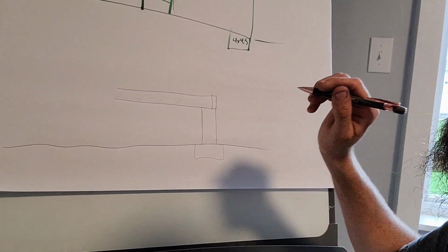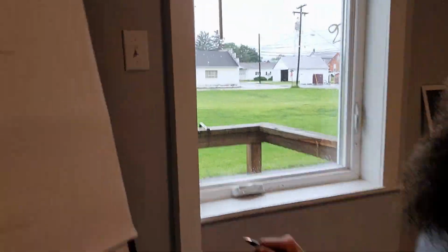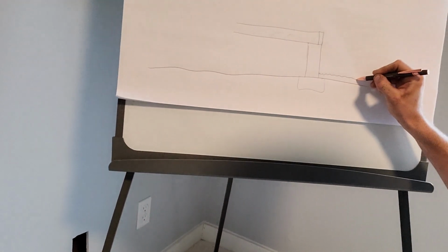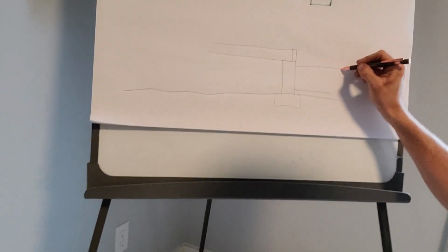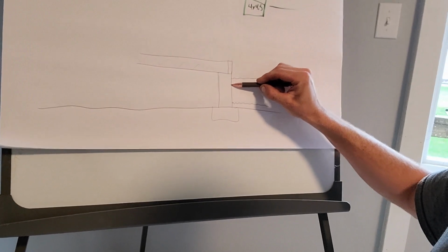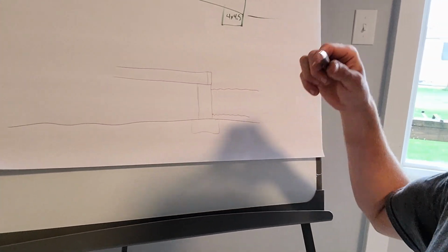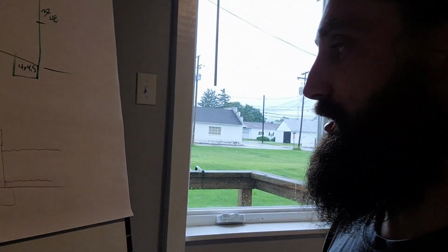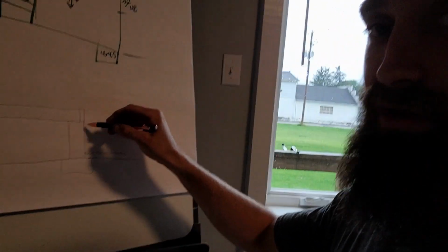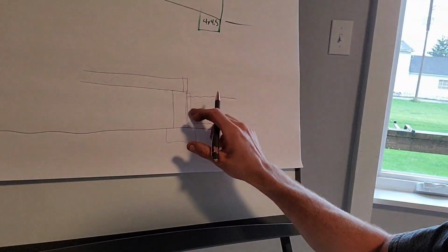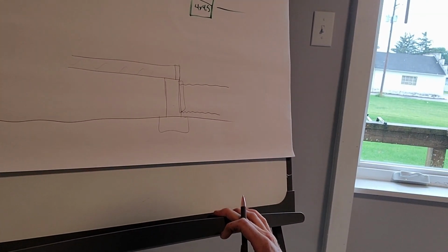Now, what we need to take note of, especially in an area like this, which was an old commercial building, is where is our exterior grade? Okay, is that grade 3 feet below the floor? Is it 6 inches below the floor? How much exposure does that crawl space foundation have? Okay, this would be true whether it was a full basement or just a crawl space. We need to know the exposure that there is on our crawl space itself.